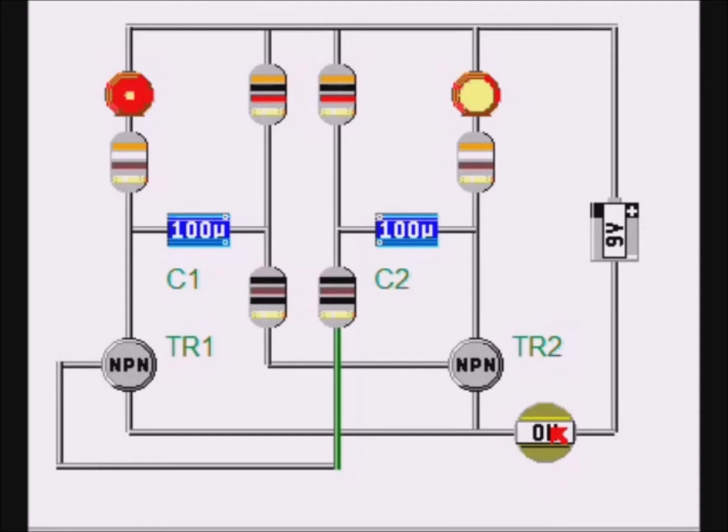We switch on and see the effect. Whenever a transistor turns off, the LED above it dims. This example includes two polarized capacitors. This means that it's important to connect them the right way around. Generally, the negative end is marked with a 0.